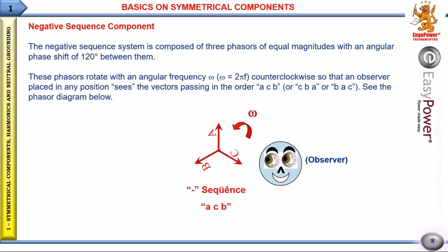The meaning of that is that for negative sequence components, the true rotating direction will be clockwise, because conventionally is counterclockwise. But since he reversed the 2 phases, the true rotation direction will be clockwise.